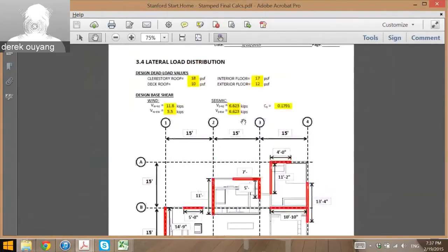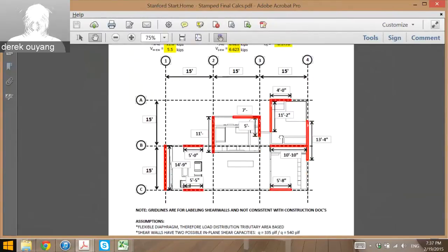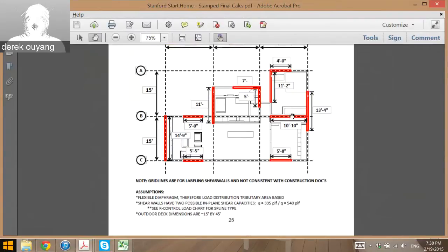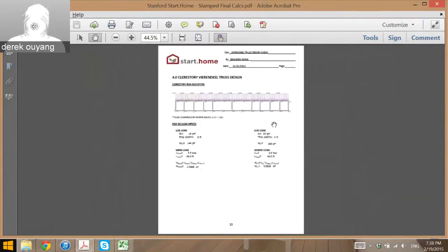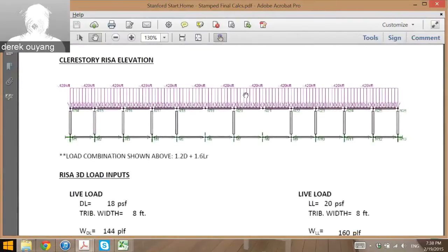Here they show clearly where the lateral system is, and we went through an exercise like this in the drawings. But when you guys maybe do a hand drawing of this, that would be a nice thing to put in the calculations. And you've clearly indicated where your moment frames are, where your core bracing is, where your concrete shear walls are. And that's nice to just put that figure in there, because from there on, then you're just checking each of those, right? You're checking in each direction, what's your capacity. This is that design of the Vierendeel truss.